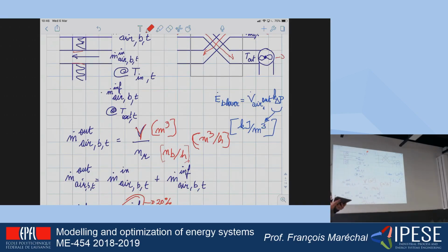So in order to calculate the amount of air that the system needs, in fact, there is a trick. And the trick is, again, to look in the norms. The norms give you rules that say how much air needs to be replaced in a given volume per hour, which is a ventilation rate. So it is going to say that, for example, the total volume of this room needs to be replaced twice an hour. Now, if you know the volume of the building and the value of the air renewal rate, then you are able to calculate the flow of air that you have to extract.